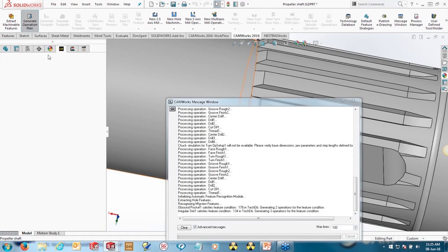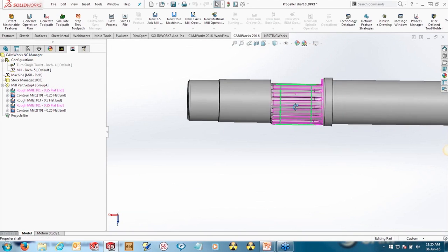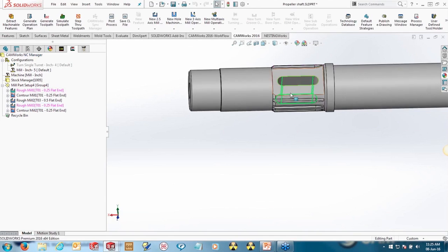Again, use the database, go through, program the pocket here. And this is basically a perfect example of using the feature recognition. What it would do is, if it can't fit the tool in that particular geometry. Now, it's trying to use a 1/4-inch tool right now. This is an 1/8-inch radius, so 1/4-inch total, but there's probably an allowance on that rough which says, hey, leave 10 thou on the walls. It's not generating because it won't let me put the tool in that region because it can't fit the tool down there.